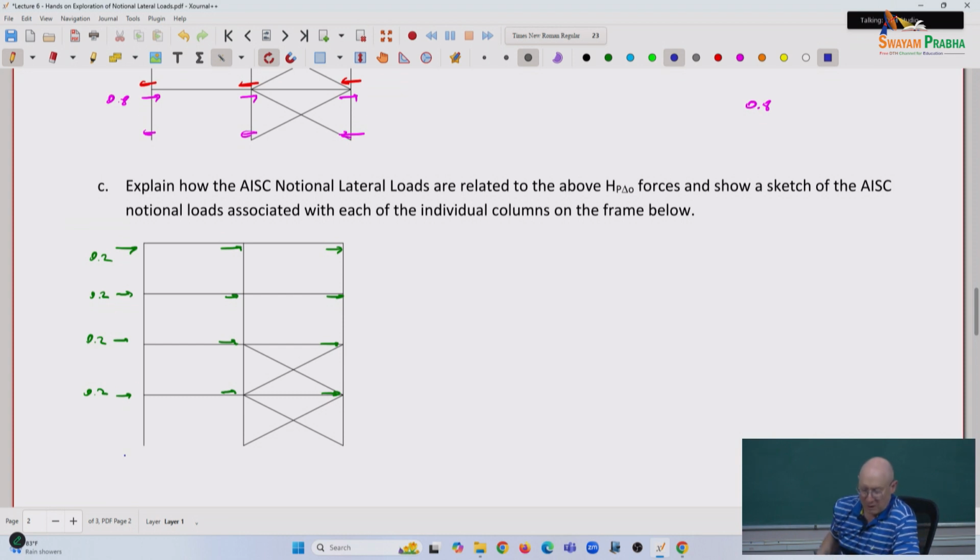Going back to the little hypothetical, let's suppose those brace bents are infinitely stiff compared to the moment frame column on the far left, so all the story shear goes to those.